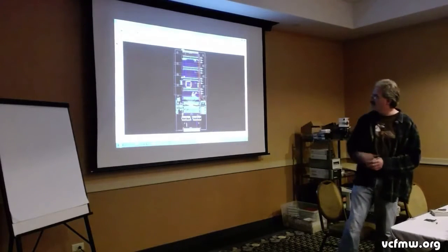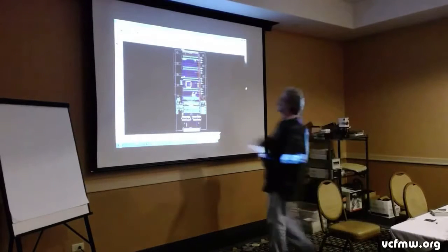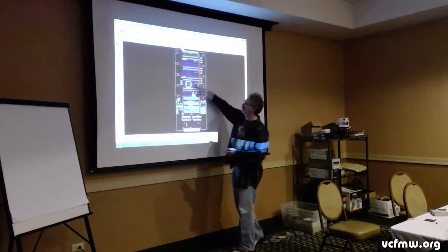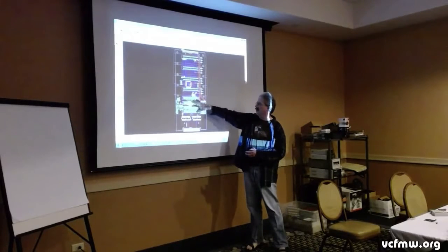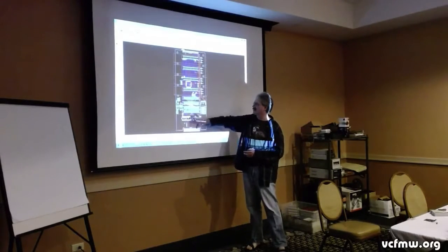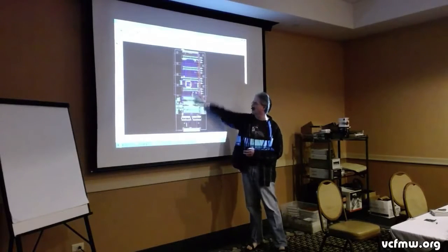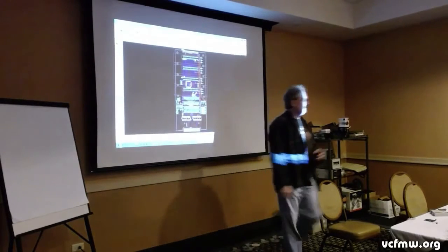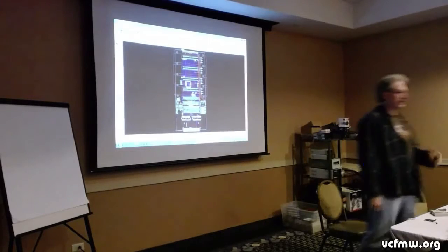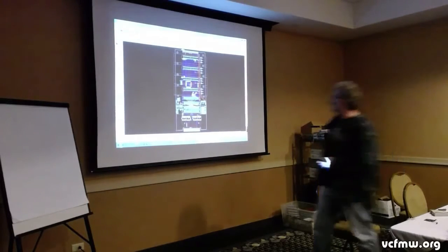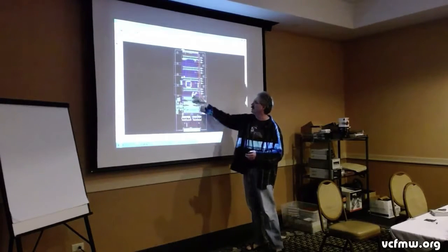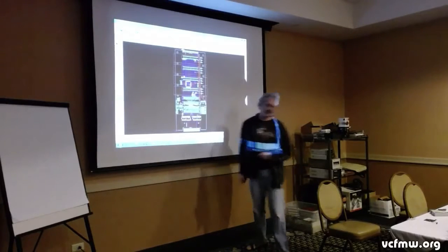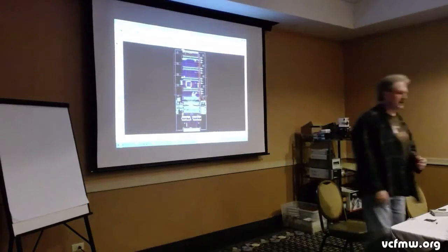Now this looks pretty complicated, but the majority of this particular design is just a bunch of wires, because this is a four-position expansion interface, and then just some IDE cabling that connects this daughter board, which has got buffers, to the main board, which has the actual expansion ports in it. And then, as you can see right here, there are some integrated circuits, some TTL logic down here, and I'll explain that in just a little bit. There's a voltage regulator, and then the main chip of the day is the CPLD sitting on the main board.